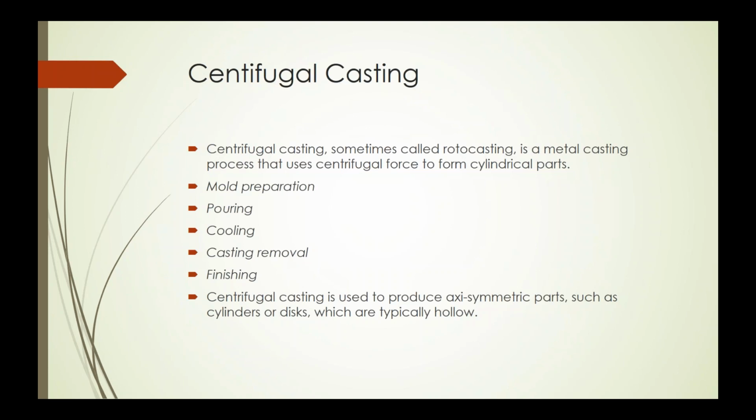And then, once you've poured all the metal, you start cooling the casting chamber or mold, and you continue to rotate it during this process. When the time is right, you open up the mold and remove the casting. And then whatever finishing processes are needed are begun.